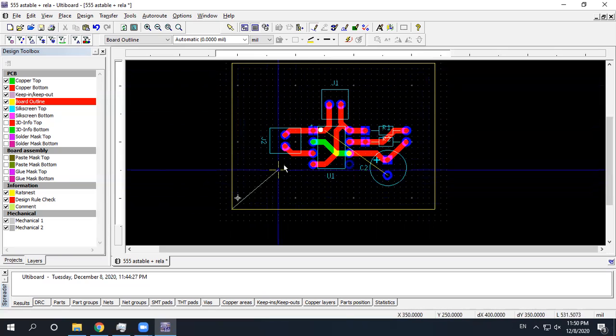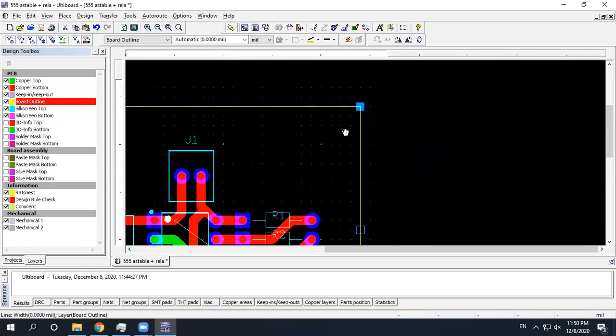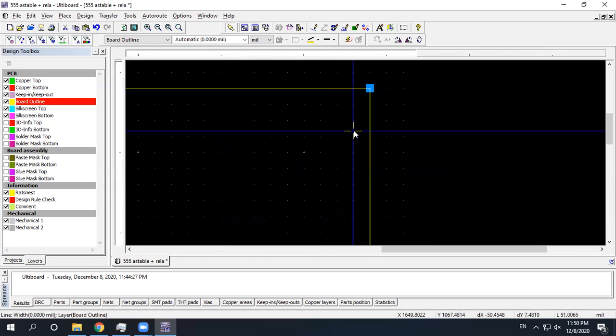So, you notice that it is still trying to draw another line. So we press an escape button here, and press escape button another time for the second time to come back to the selection tool and release the pencil tool. So what we have now is that there are four lines that are making up a rectangle, and this is not a single rectangle. So we can adjust the size of these lines.